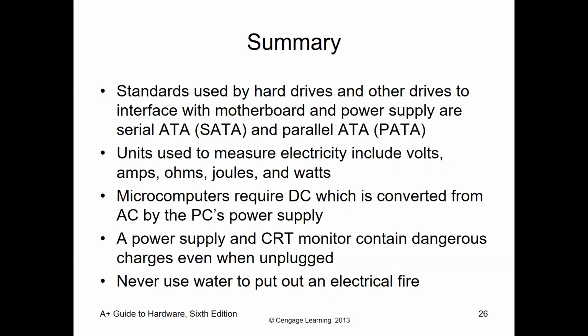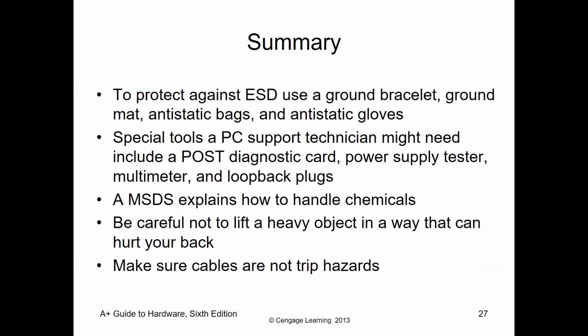A power supply and CRT monitor contain dangerous charges even when unplugged. Never use water to put out an electrical fire. To protect against ESD, use a ground bracelet, ground mat, anti-static bags, and anti-static gloves.